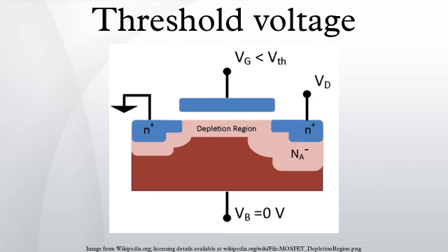This kind of tunneling, called Fowler-Nordheim tunneling, where A and B are constants and E is the electric field across the gate oxide. Before scaling the design features down to 90 nm, a dual oxide approach for creating the oxide thickness was a common solution to this issue. With a 90 nm process technology, a triple oxide approach has been adopted in some cases. One standard thin oxide is used for most transistors, another for I/O driver cells, and a third for memory and pass transistor cells. These differences are based purely on the characteristics of oxide thickness on threshold voltage of CMOS technologies.